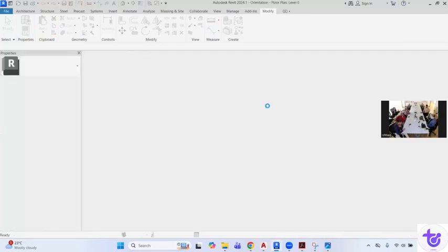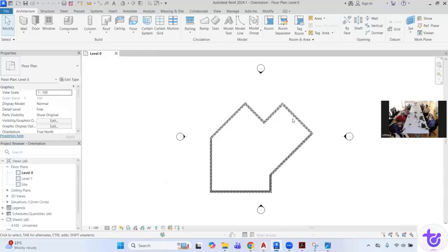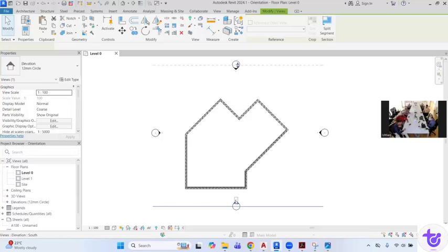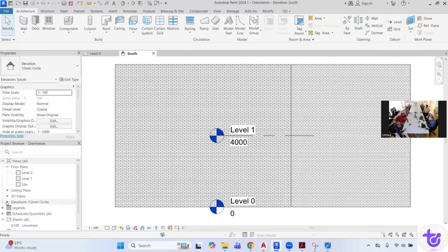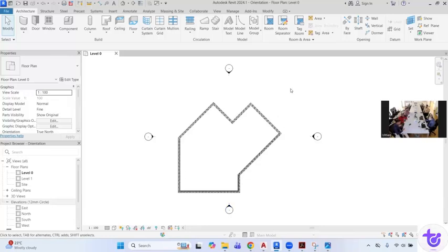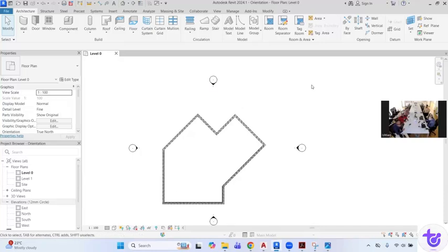You see, in a project, there are two things. One is the project north and the other is the true north. Project north is something, because in Revit, the north is always upward. If you click here in the architecture only, it is giving you the south elevation, because you are standing on the north side, you are reviewing on the north side, and this is the south side. So by default, this is upward. But if you talk about the true north, it can be any direction, here, there. This is the real north as per the geolocation.